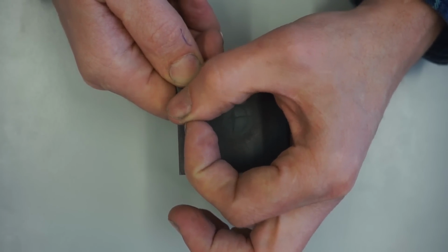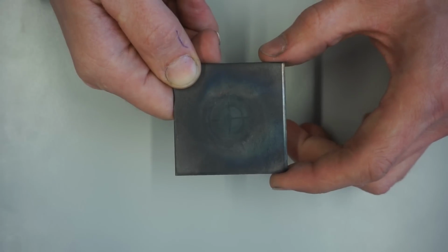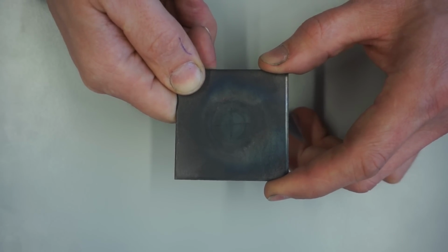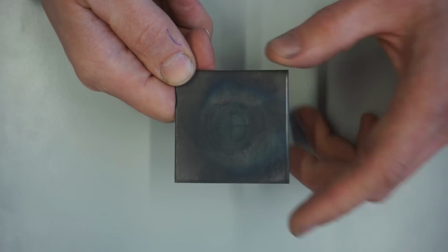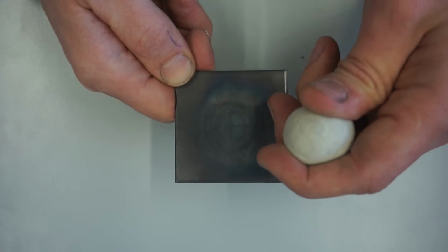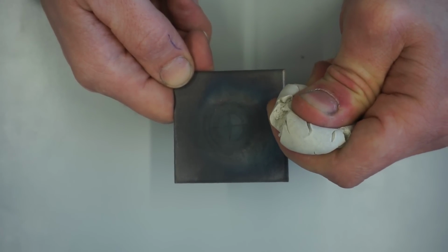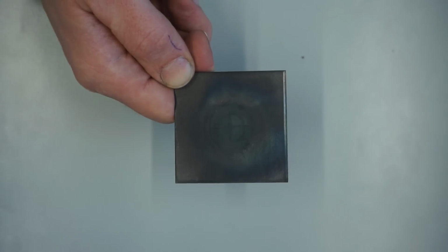This in turn is experienced by the heated spot as radial compression. As temperature rises, the compression stresses rise and sooner or later exceed what the heated spot can take. Then it begins to behave like a very strong putty and flows in the direction which is the least stressed. And here, this is the thickness direction.